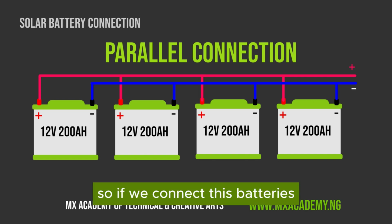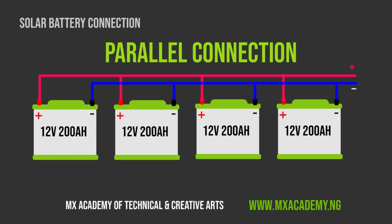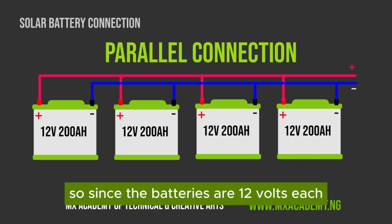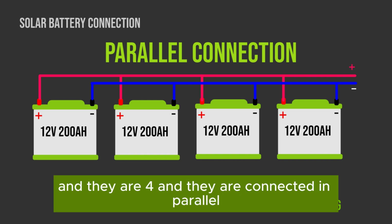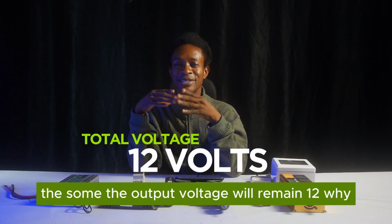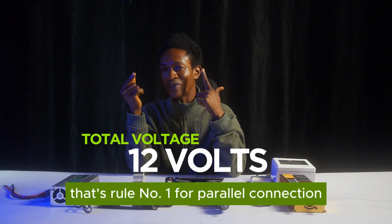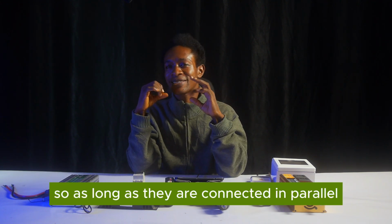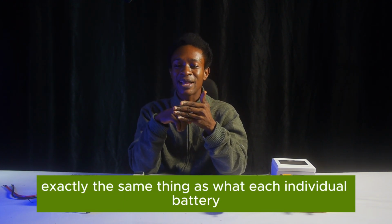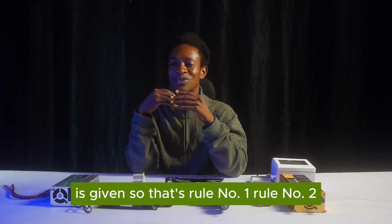If we connect these 4 batteries in parallel, what happens to the voltage? Since the batteries are 12 volts each and they are connected in parallel, the output voltage will remain 12. As long as they are connected in parallel, the output voltage will remain exactly the same as what each individual battery is giving.